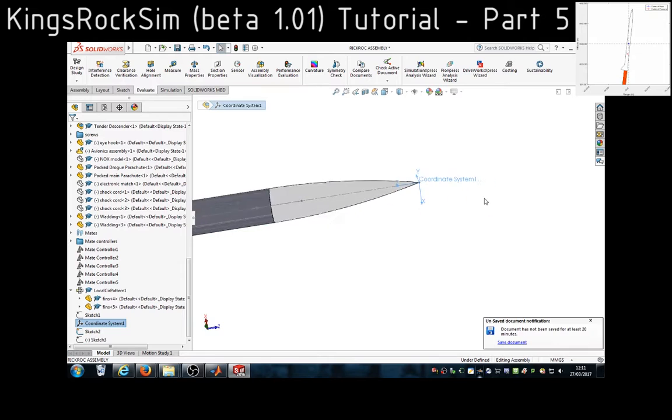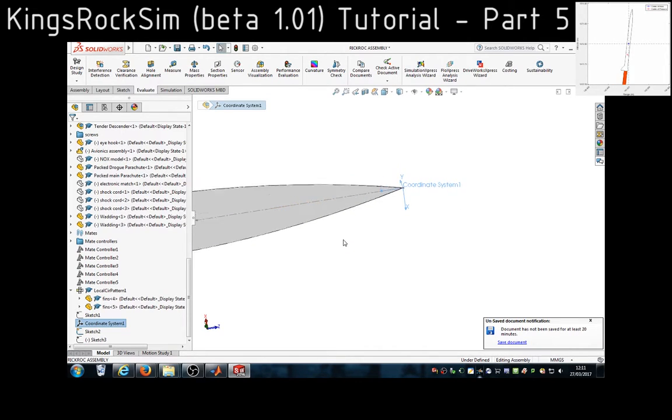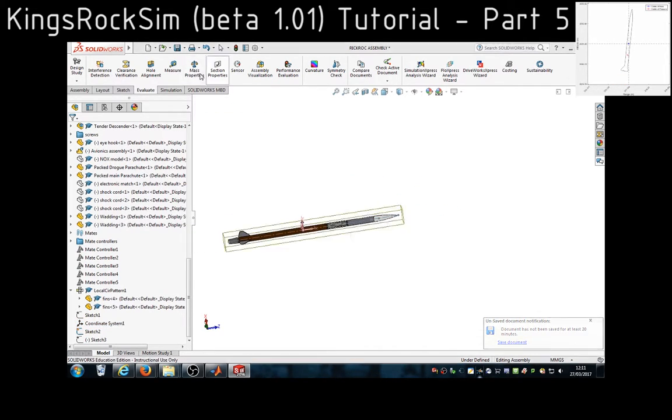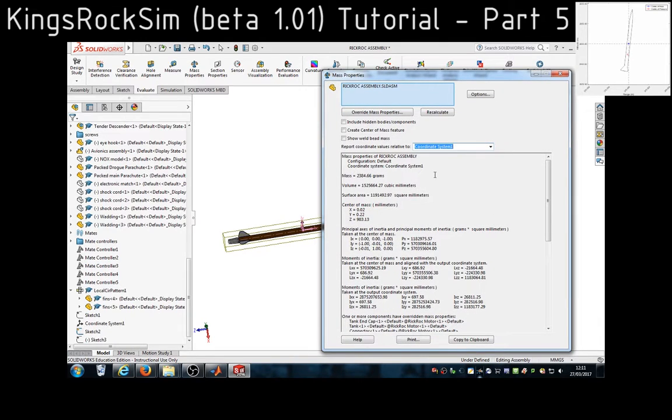The distance of the component from the nose tip. Now, the distance in this case is the distance to that component's individual centre of mass, which you can get from SolidWorks. Treating the total dry mass as a single component will actually make calculations for the centre of mass, and especially the mass moment of inertia, inaccurate later, so you do want to be specific with these component details. But for the purpose of this video, we'll just stick to the total dry mass so we have fewer components to deal with.